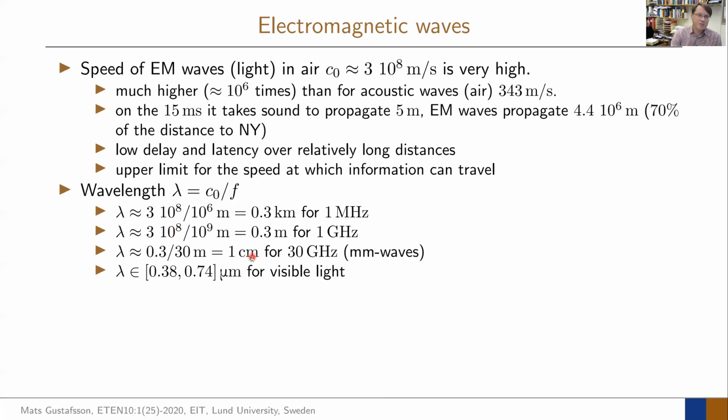It's 1 centimeter. And when you think about antennas and communication systems, most of them sit around 1 gigahertz. So it's very, very easy to normalize to 1 gigahertz. And then you can get all these length scales directly in this communication band. So you say 60 gigahertz. Okay, how big is 60 gigahertz? That's half a centimeter. No calculators, nothing. Because you can all divide 0.3 by 60 in your head. And then you can understand, because what we will see is that antennas like to be half a wavelength, which means that they give you a reference to the size of these antennas.